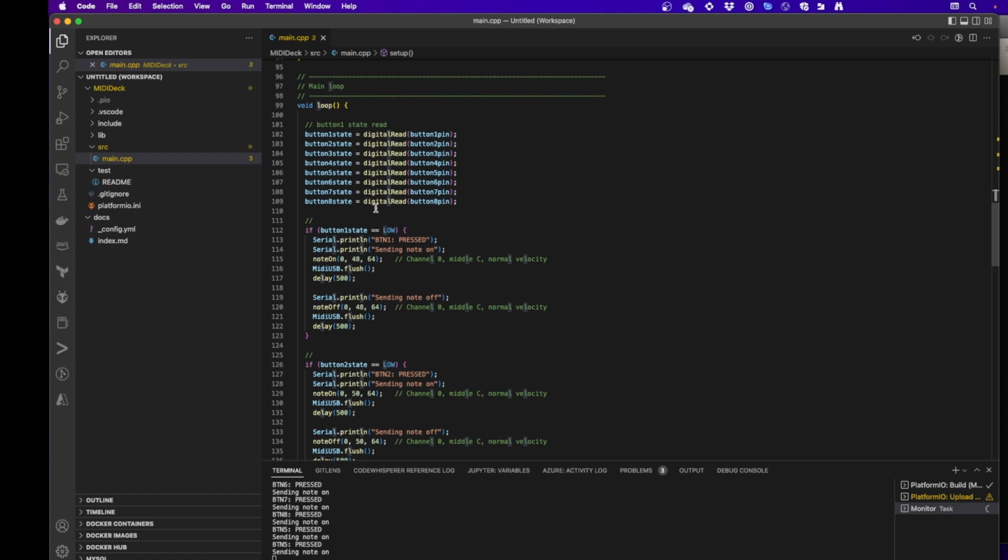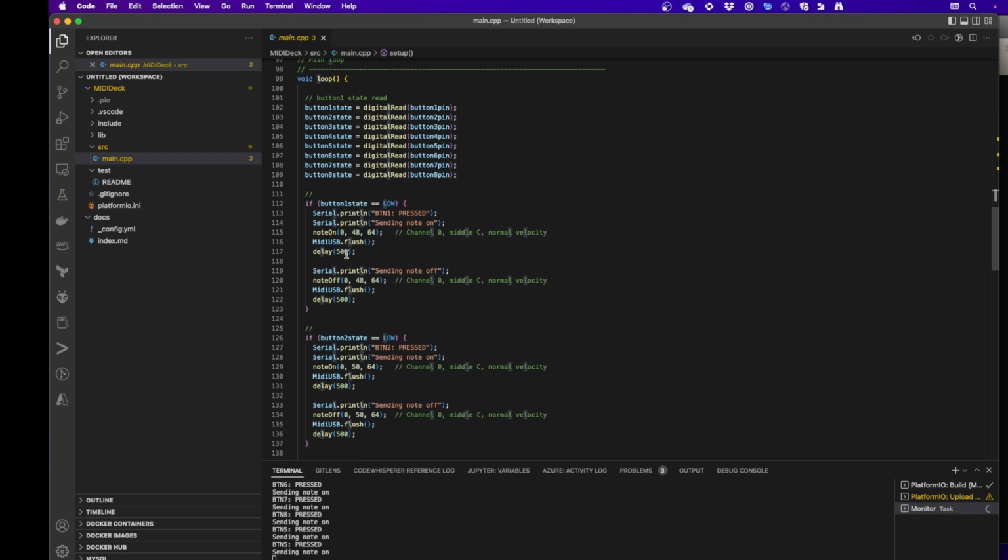And here it is, the digital read in the main loop. So all we do is when it comes inbound, we can change this delay 500 to more like 100, I think. I thought I did. Yeah, we'll change it to 100 because you don't need much. That's really to get around the debouncing. That is a primitive debounce. I suppose in hardware we could debounce it some other way, like with an RC circuit, or I could use a 555 or something, but this is easy right now.